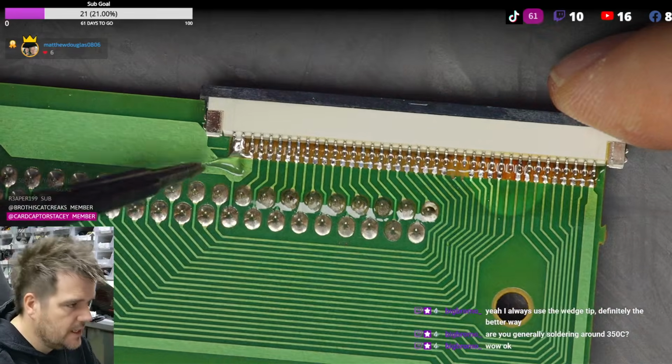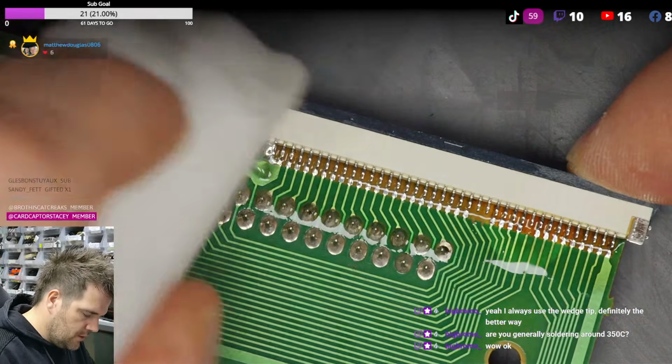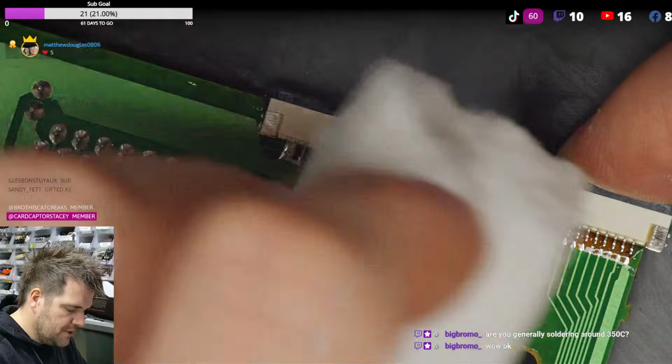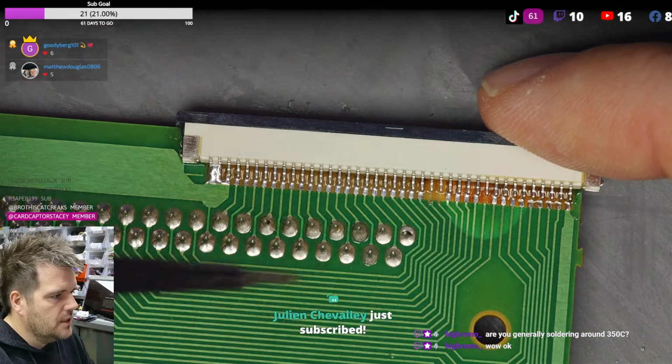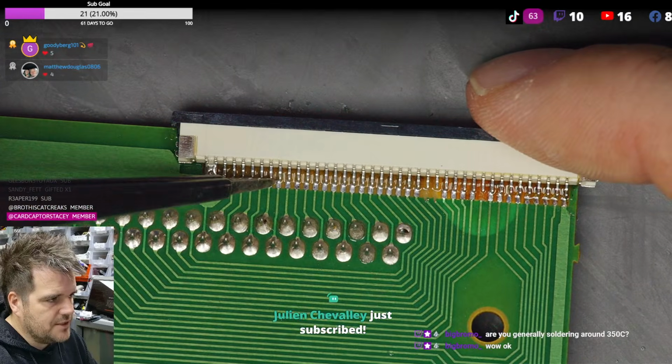The only warning I'd say, if you've seen the other streams, you'll probably know, if you're going to drag solder, there are certain chips that you can drag solder on, but you need to be super delicate. So like on these, we're just dragging down, not really taking care of the pressure of the tip, and everything's fine.